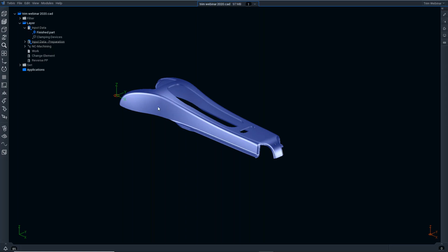Okay, so this is a solid model. We have an inner surface, we have connecting flanks, and we have an outer surface area. To make the programming process more simple, we're going to pull the inside surface off of this model. That way we can use that to drive the tool direction. So when we're working normal from surface, we'll have the tool direction always perpendicular to this surface. So just to see how quickly that works.